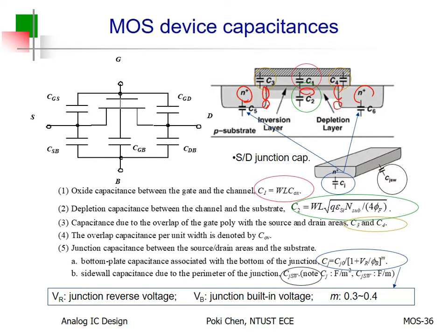The side wall, besides channel, connected to channel, has very few parasitic capacitance. Got it? If the channel is here, then this side wall has much less parasitic capacitance. For the other 3, 1, 2, and 3, they have 100% of the parasitics.